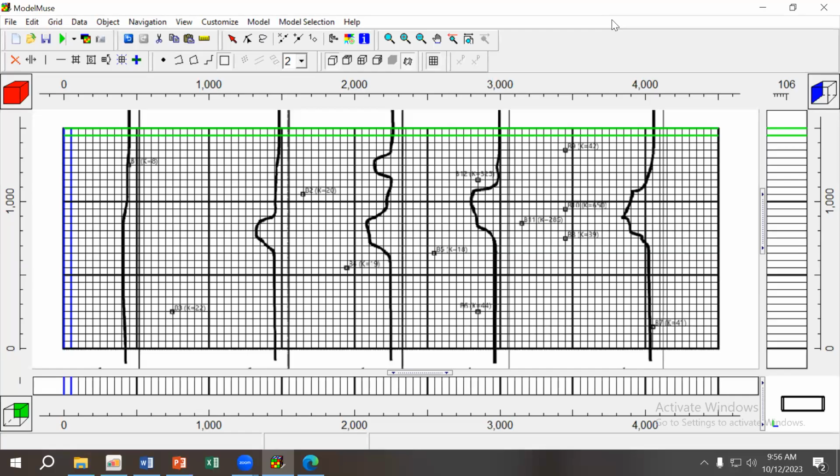If the head here is lower than the head here, so I measure, for example, the head would be here, then the flow Q will go from the river vertically to our aquifer. And you can apply Darcy's law for this.